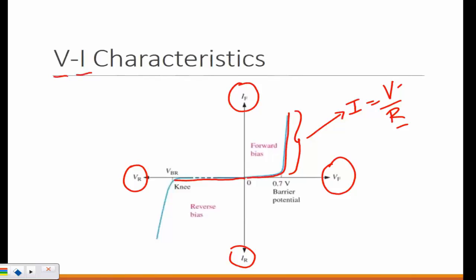If you reach that point, let's say the diode breakdown is 50 volts, right? If you don't apply 50 volts, you're not going to be in the breakdown. Correct? If you apply, let's say 5 volts, are you going to be in the breakdown? You're nowhere close to the breakdown. This means this is the highest voltage in the reverse bias you can apply to safely operate the diode. Does that make sense? That's the breakdown voltage.